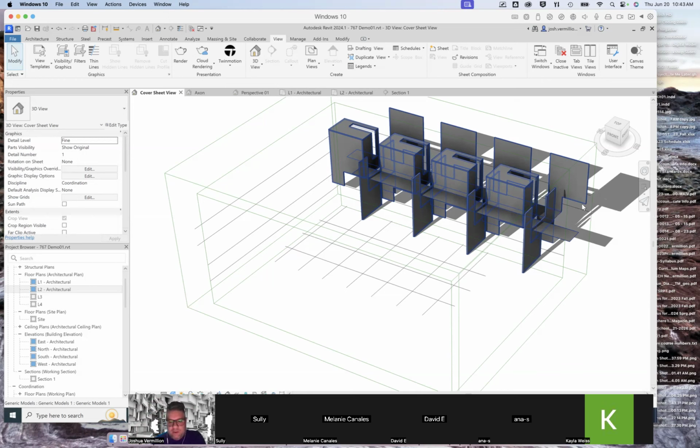So if I'm thinking about what I was trying to accomplish and also what I was reacting to, repetition and modularity, and some of the opportunities when I was placing these things, I can say, okay, these can become light scoops, vertical baffles to bounce light down into some of the deeper parts of the building. It looks like I have just a little bit of top light and side light here on the north and east side of these boxes. And on the south face, I'm going to have a lot of daylight and a lot of sunlight.